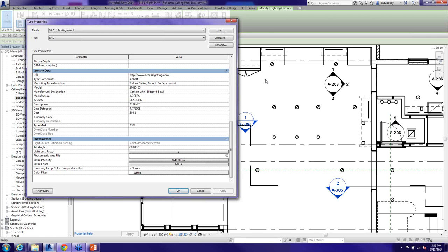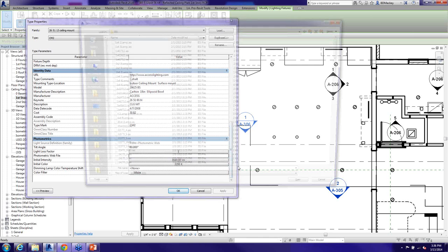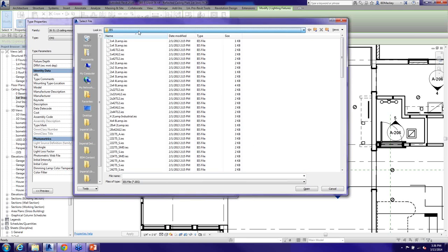As you're doing this, you might have an IES file, but you've got to make sure everybody has access to that. Okay, so with that said, I can hit the little browse button, go to the out-of-the-box Revit IES files, and if I knew what all of these mean, I could go through and grab an IES file, right? They're all different. They've got different things you're looking for. I'll hit open, and now you'll see it's using that IES file.